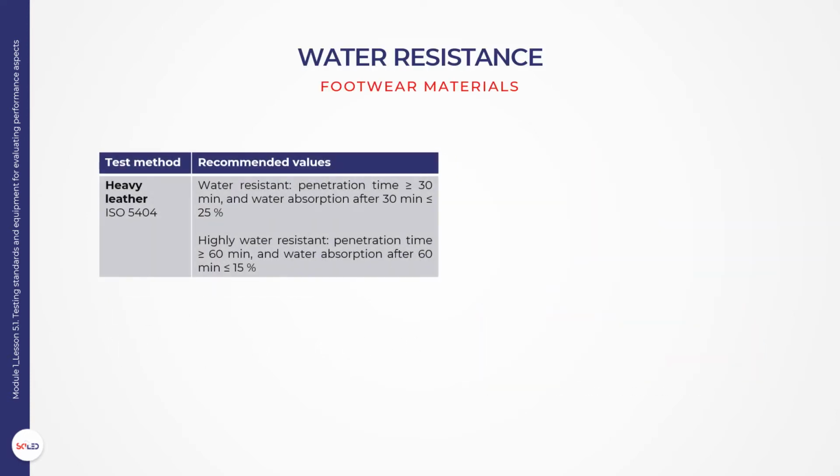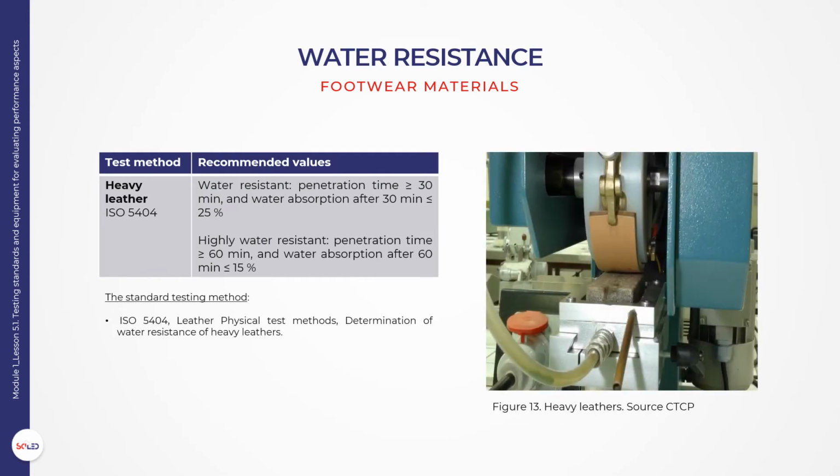Water resistance of heavy leather. Test method applicable to soles made of leather. The test piece is continuously wet on one surface and is flexed and compressed in the same manner as the sole of a shoe during walking. This enables various aspects of heavy leather water resistance to be measured with respect to time.